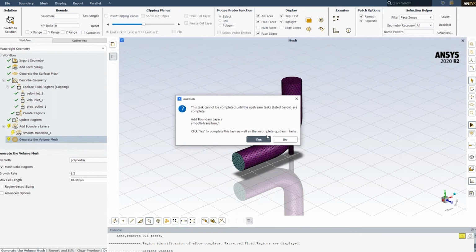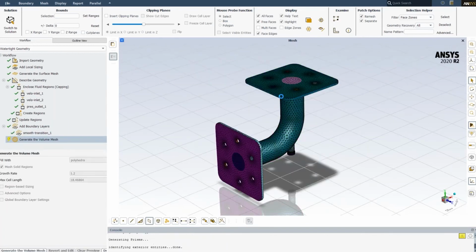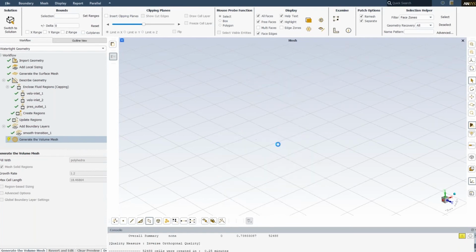Now, of course, in reality, for those of you that have done CFD before, you do have to put some time into getting the mesh resolution right. That's an iterative process, so you may run a CHT analysis and then run a refinement. That's basic for any sort of analysis.